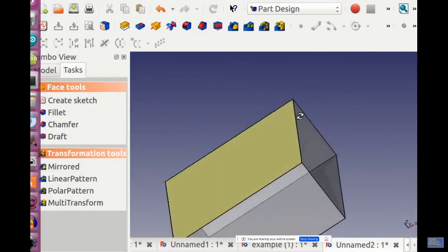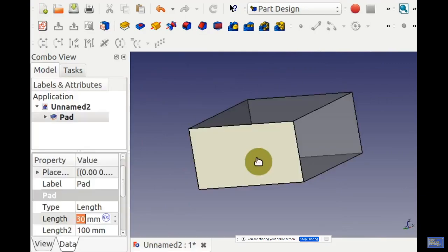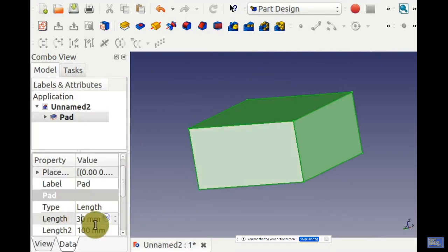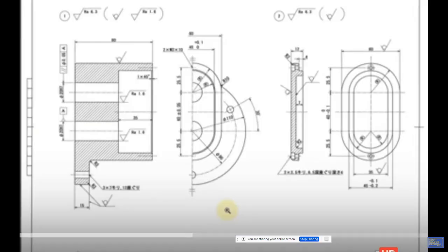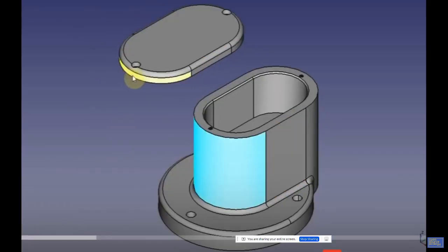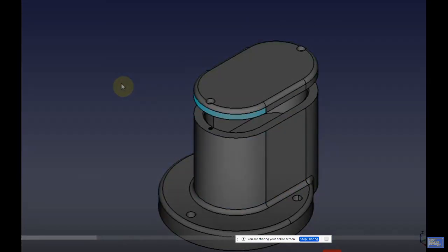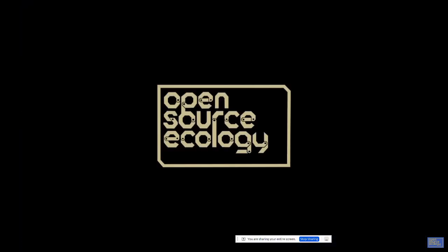The tree view also allows you to change parameters. Select object, click on data, and you can change dimensions. You can use the sketcher to reverse engineer parts. If you have existing 2D blueprints, you can draw the complete assembly part by part. That's that. So all kinds of geometries. But let's do a little exercise.